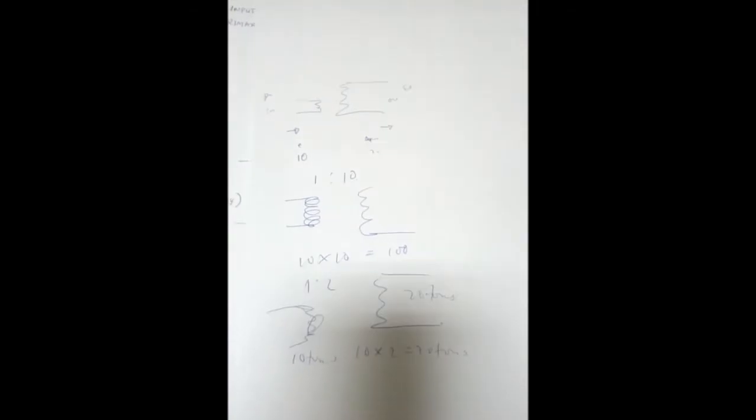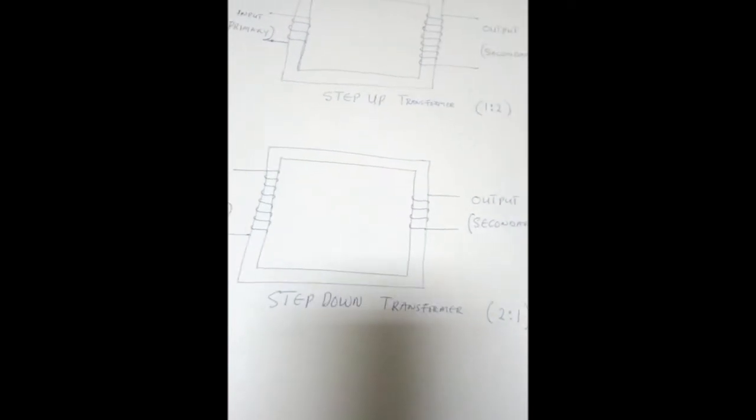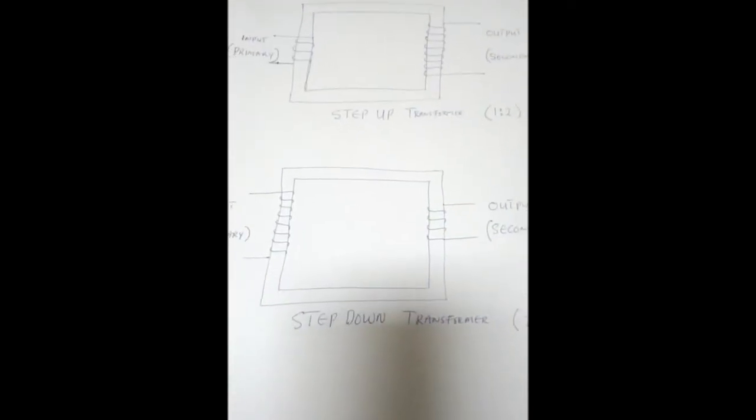Now in transformers, sometimes when you get a transformer, you will see it has frequencies. We have the 50 Hz or 60 Hz, or different Hz, which is the frequency of the transformer. And it is important that you observe that, especially when there's an issue with one and you have to replace it, you have to be very careful about the frequencies.